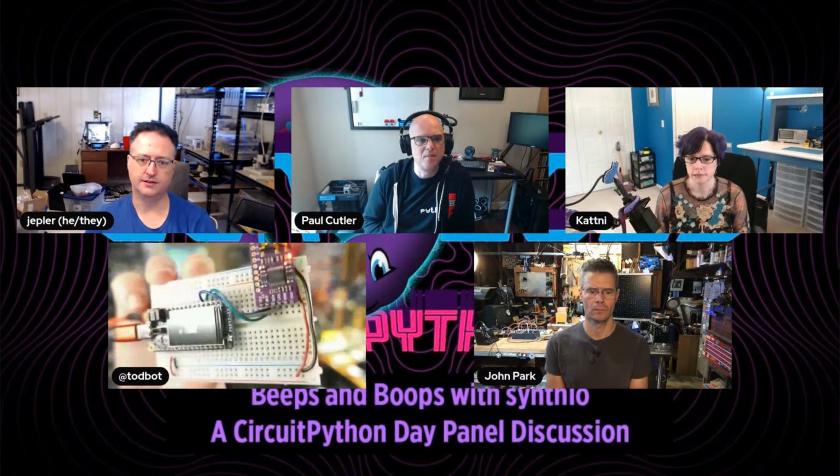But really, a lot of boards. Somebody did it. Todd, you did one with ESP32. Which ESP32 was that? The S3? Both the S3 and the S2. So the answer is a lot of stuff works really well. I think I would look for something that works with I2S, which seems to be the best quality of audio. So RP2040 will do that. The Espressif will do that. The SAMD51 will do that.